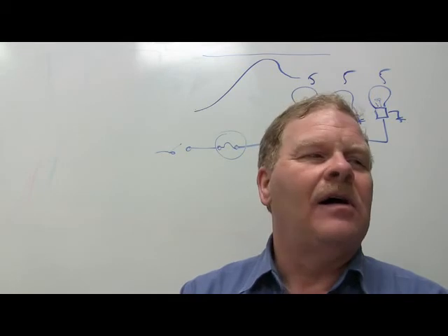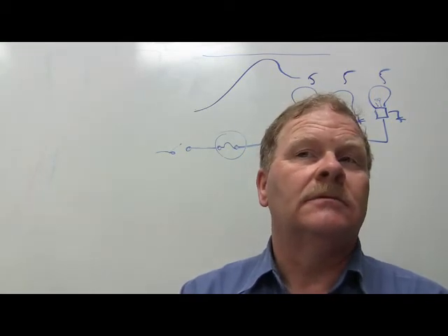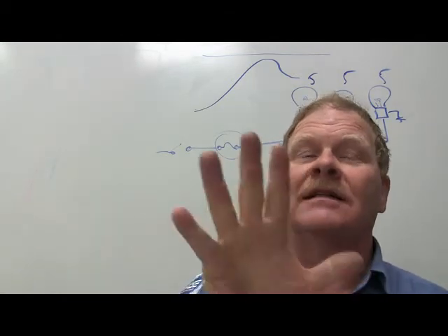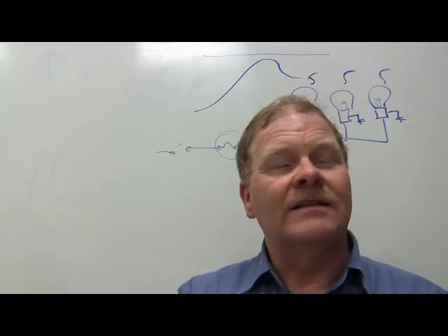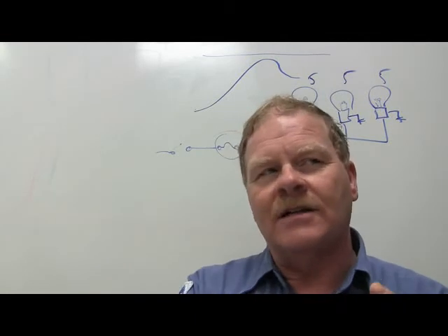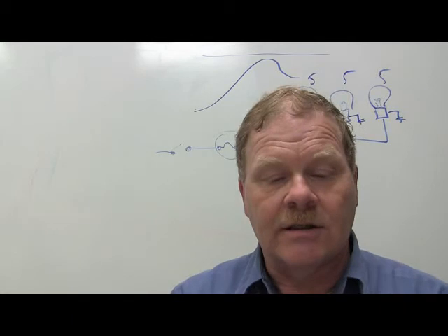What about the door jamb switch? You open the door, the button comes out, and it's lighting up your interior lights. So when it's at rest, the lights are on because you've got the door open. When you close the door, you're mashing the switch and it's opening up. See? So you've got normally closed and normally open switches.